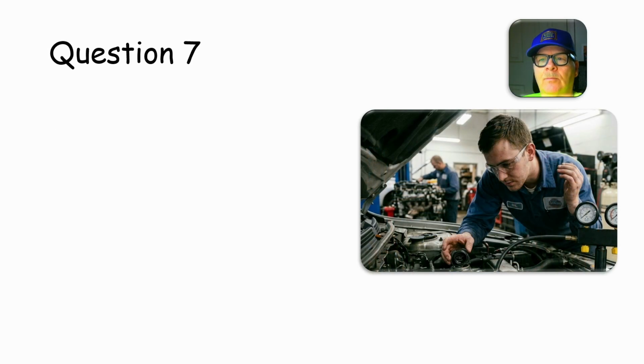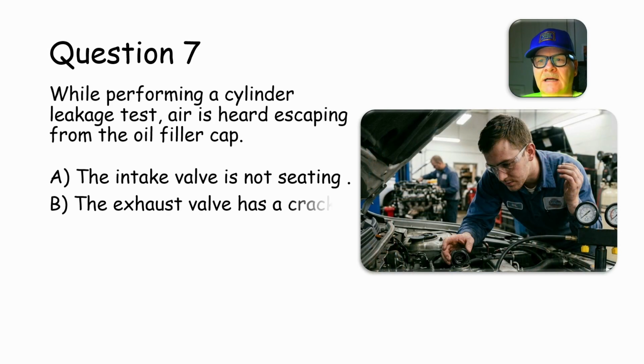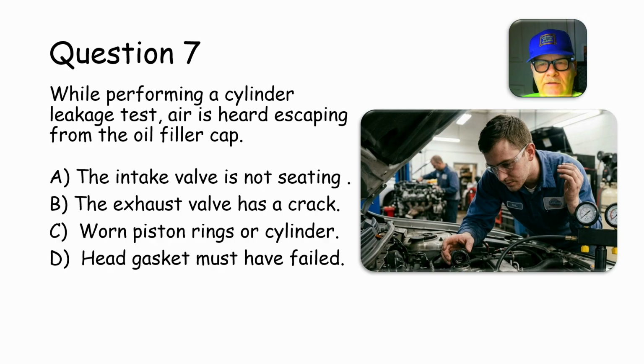Question 7. While performing a cylinder leakage test, air is heard escaping from the oil filler cap. Does that mean the intake valve is not seating, the exhaust valve has a crack, worn piston rings or cylinder, or the head gasket must have failed?